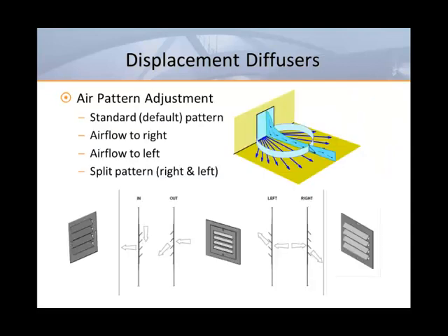Adjustable diffusers are recommended because of the adjacent zone. It's important to provide some means of fine-tuning the air pattern. As anyone in the construction industry knows, things don't always work out perfectly, and sometimes spaces change purpose. For these reasons, adjustable diffusers are recommended to accommodate changes in room layout or seating locations.